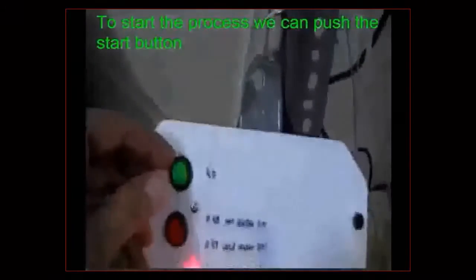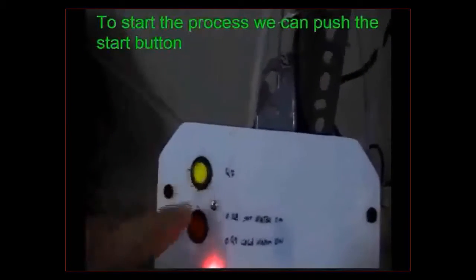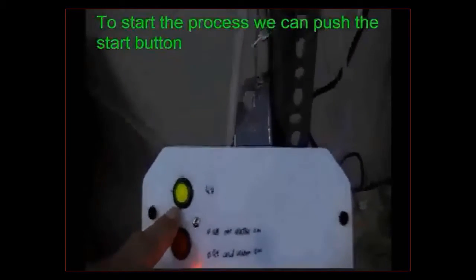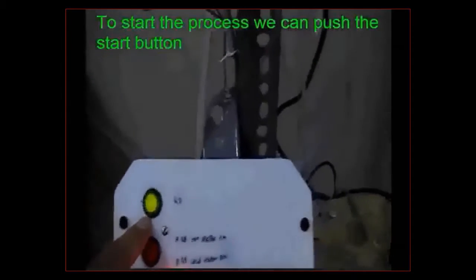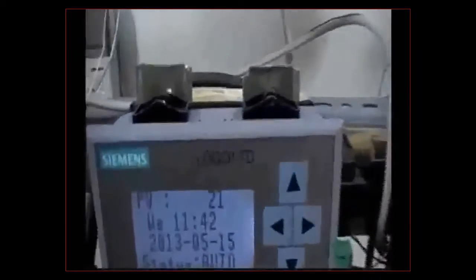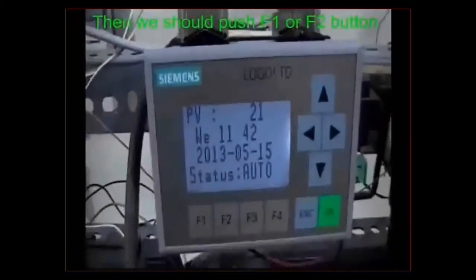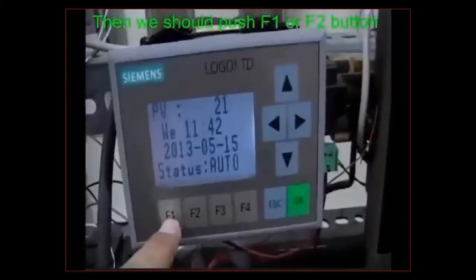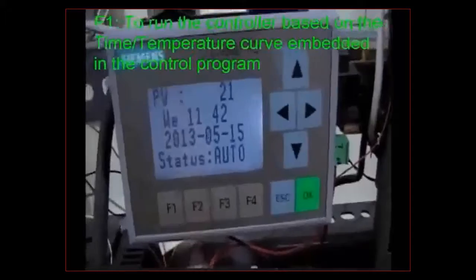Simply, to start the process, we can push the start button. The light inside the button turns on. That means right now the system has started, and the backlight is on. And in this case, the system is waiting for the operator to push either function 1 or function 2.